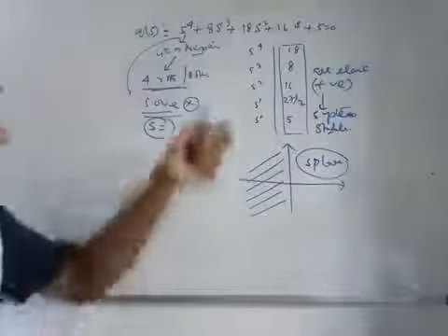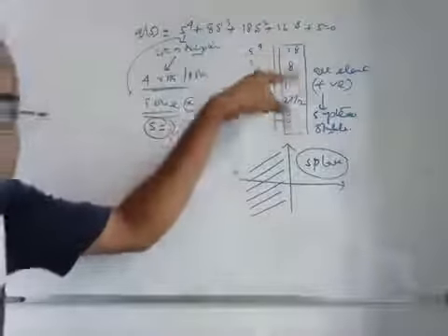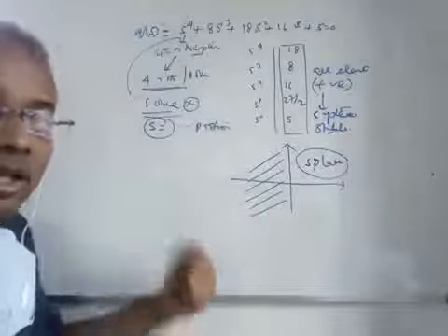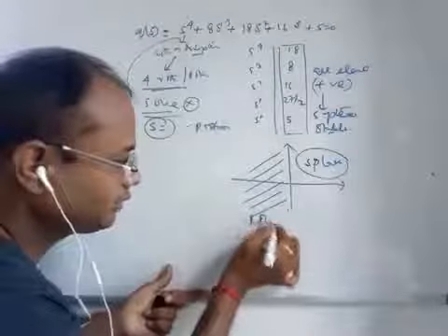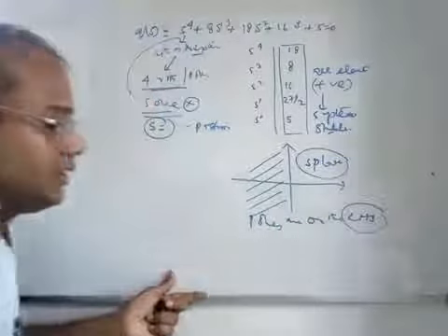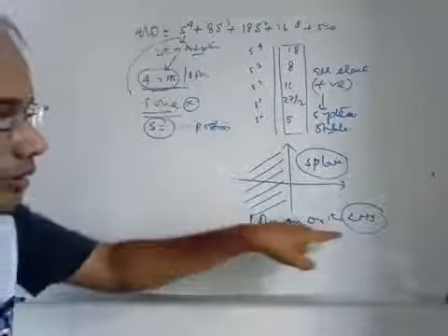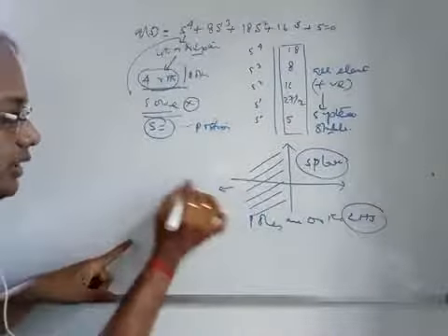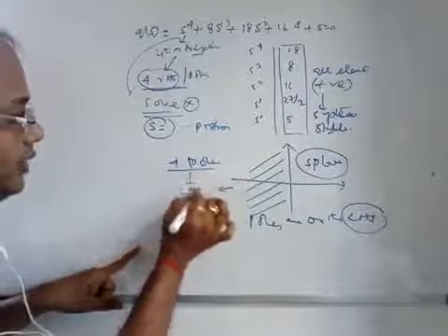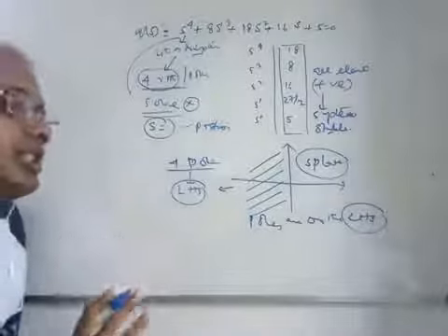But by using the Routh array, what you have seen, if all the elements of the completed Routh array, the first column elements, are positive, the system is stable. And in other words, if the system is stable, that means the poles are on the left hand side, definitely. And how many poles are there actually in the system? 4 poles. And if all the poles are on the left hand side, that means there are 4 poles on the left hand side. This is the conclusion. Okay, so comment on the system stability.